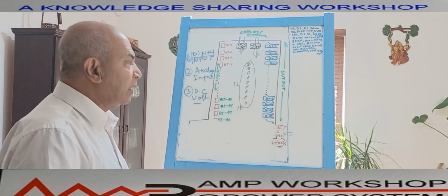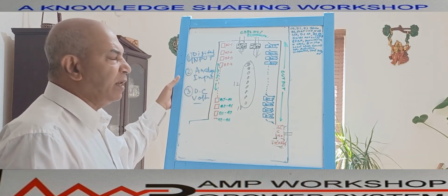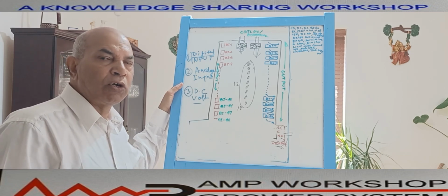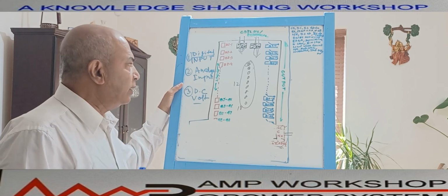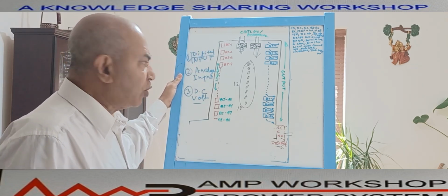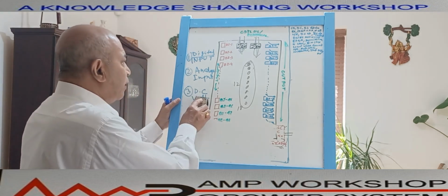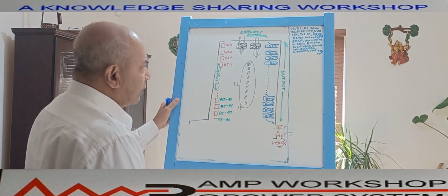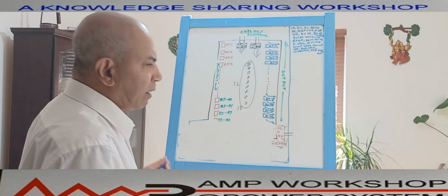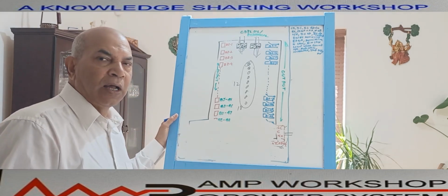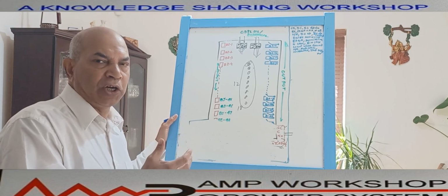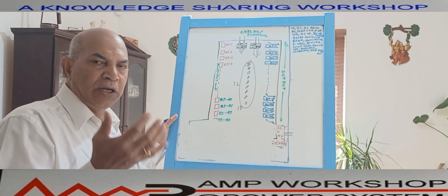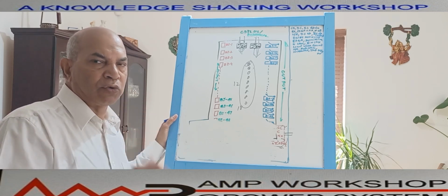Similarly, this digital relay has various digital inputs we can provide. Those digital inputs we call binary inputs. As I said, a binary input means a potential-free contact coming from the field. How do we connect it? Suppose this is binary input 1. What are the main signals we provide to the protection relay to interface with the control, indication and alarm system or control system of the switchgear?